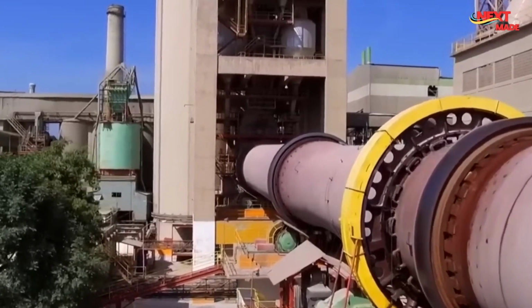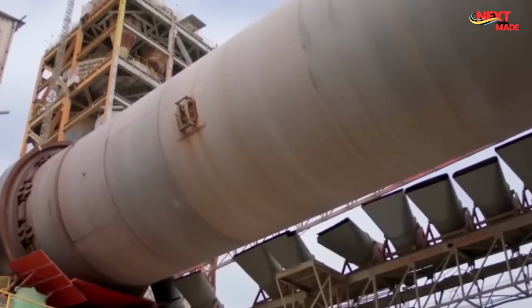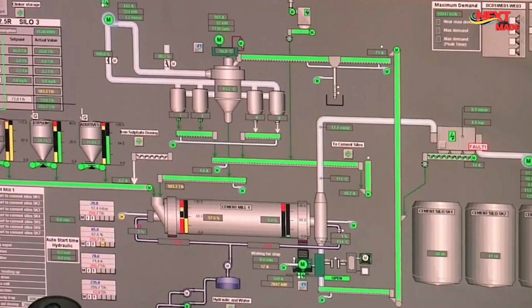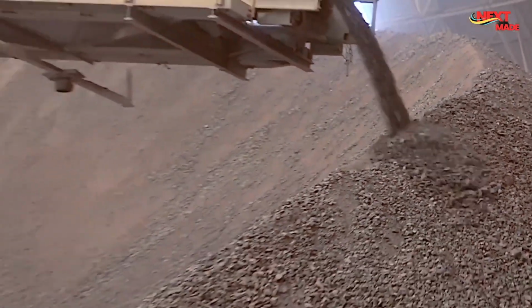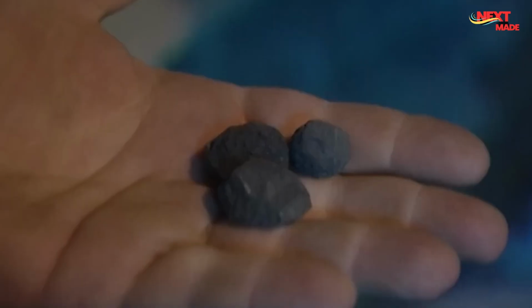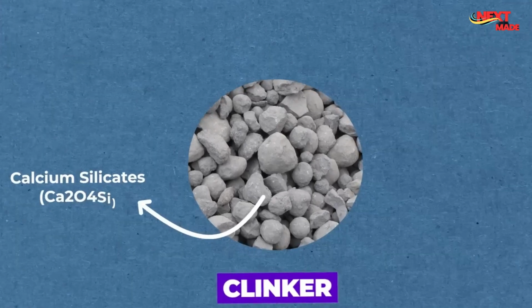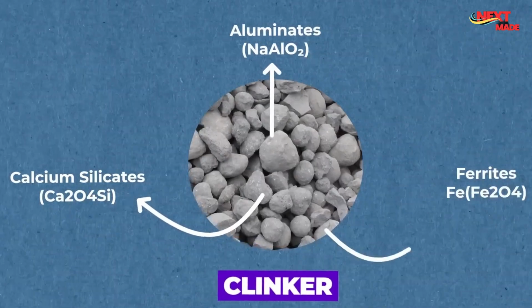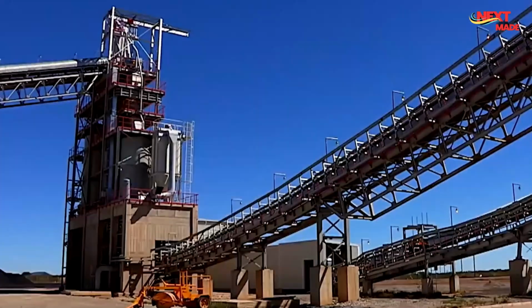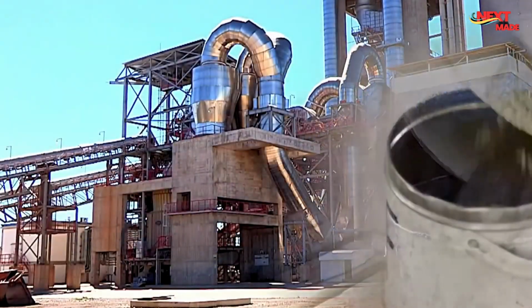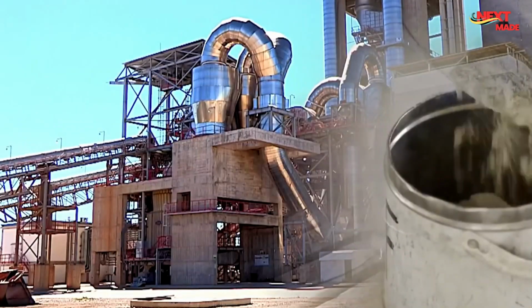Now that the cement is ready, it's time to source the aggregate. Aggregate is the most important component of concrete, comprising up to 75% of concrete by volume. When it comes to composition, aggregate is composed of both gravel and sand. The sand is added so the spaces in between the gravel are completely filled, thereby giving the concrete stronger bonding and consistency. A well-graded aggregate, which is a balanced mixture of coarse and fine particles, reduces the requirement of cement, thereby making the whole process much more cost-effective.